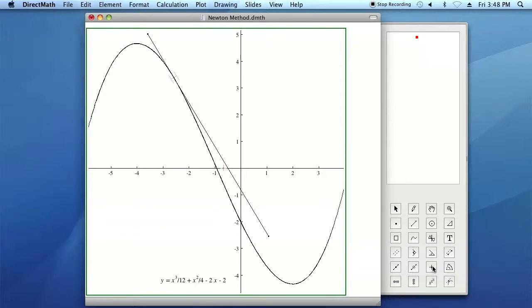Simply clicking the vertex constraint fixes the point in place so we can't move it. To make this a little bit more useful, I'm also going to attach a label to the constraint. What the label allows me to do is specify where this point will be, and I'm going to do that by simply editing the label so it forces the point to lie at a particular point in the drawing.